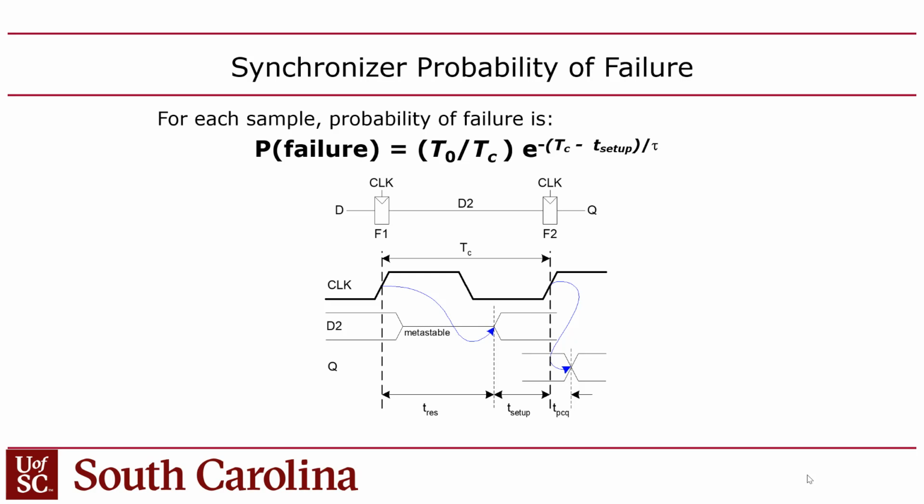We still have tau, and then of course you have that first argument there, which is basically saying, if you're going to calculate the time between failures, you have to calculate two components. The first is that you'll go into metastability on the synchronizer. That's one. And we multiply because it's an AND, both have to be true. It's got to also not resolve itself within TC minus setup. So we have two things go wrong. One, the user hits the button at the wrong time. And two, this guy just randomly takes too long to go out of metastability. Those two things together will give you this expression, which is the probability of having a failure. That's assuming, of course, you have one synchronizing flip-flop here.